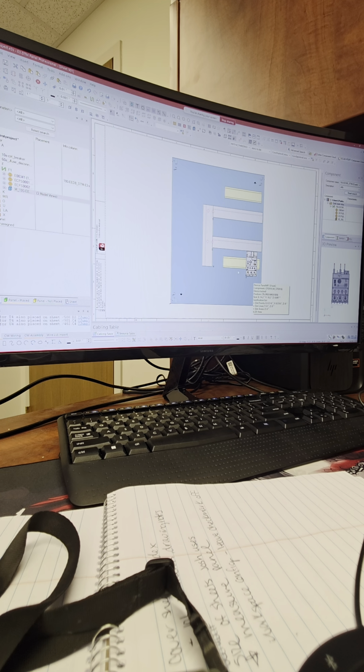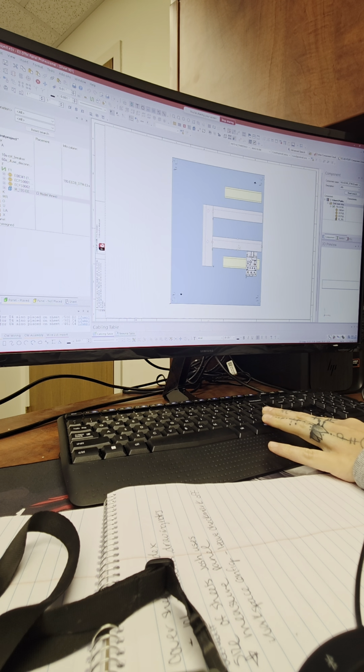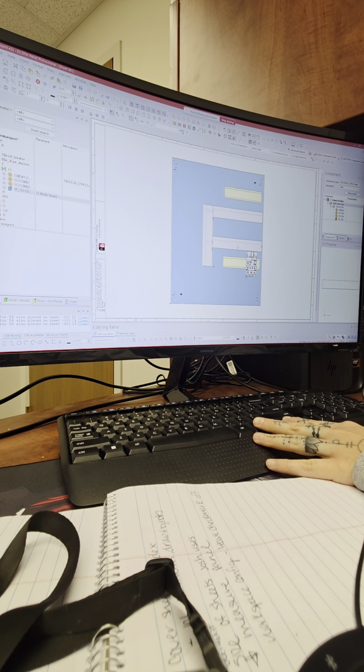But again, for your design, I would delete the second duct, the duct right above it. So I would delete that one. Actually, don't delete it from here. Undo this once. Actually, I guess it hasn't been deleted yet. Always jump from the model to your device tree structure, because you always want to delete it from the project. So Control left click. Control left click till you see the highlighted item in your device tree structure on the left.